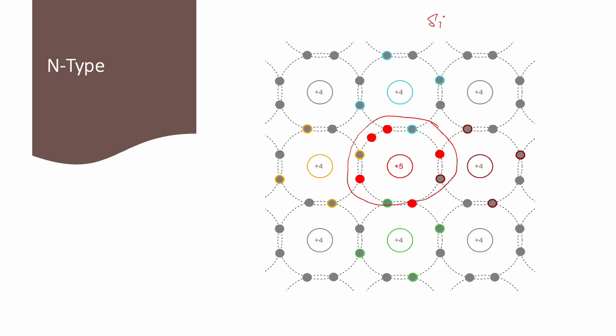So this is a pentavalent type of dopant atom, meaning this dopant atom can replace some of the silicon atoms. In this case, this is the dopant. And because they have one extra valence electron, they become negatively charged ions, with a net charge of -1. This extra electron is not tightly bound to the nucleus and is free to move through the crystal lattice.